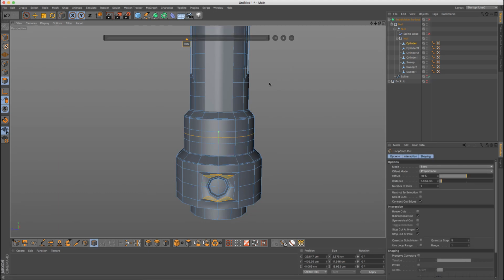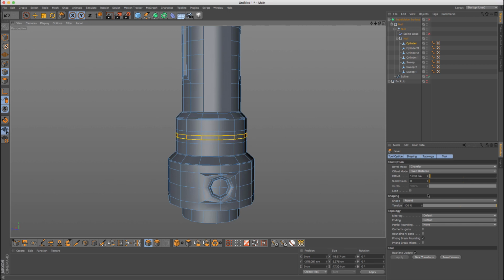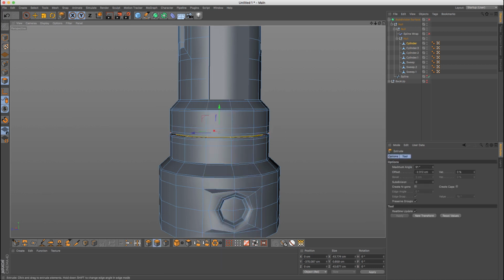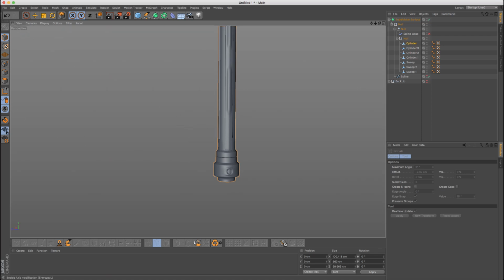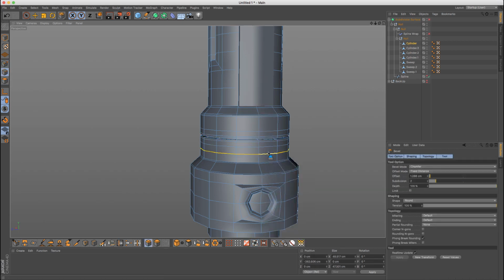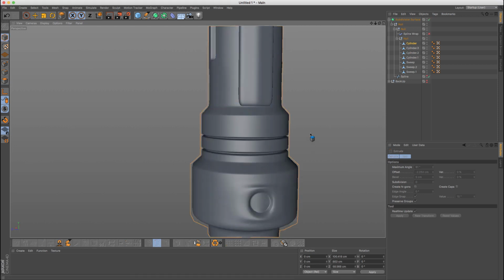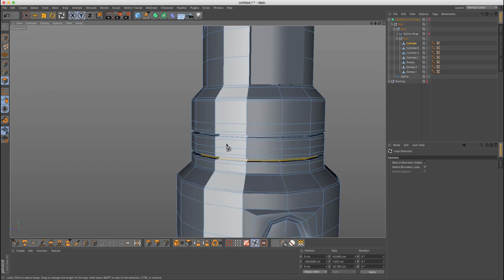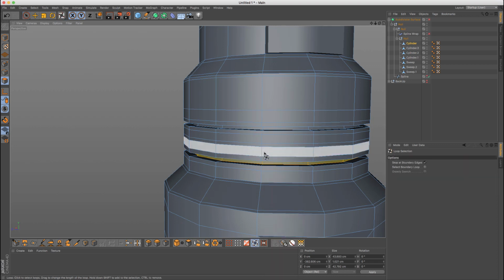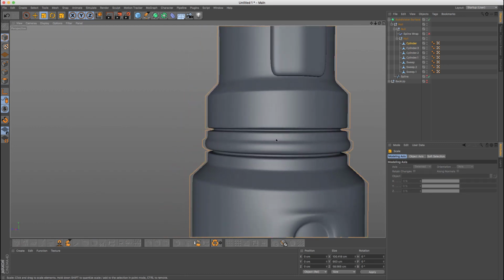And let's do here the same that we did before. So I'm going to select this loop and add the bevel and make sure that I have 2 subdivisions, and we're going to do extrude inner, same as we did, and top, like this, and there we are. Maybe I can do even one more. Like that. And what we can do maybe here is add an extra edge loop so that we can push this loop outwards. So this loop we're gonna kind of scale up, and this edge loop that we just added will allow us to have a smoother transition.